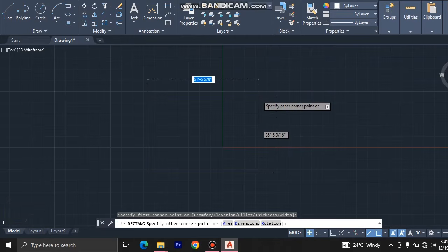As you can see, that is it. So put in the dimensions in inches. I've told you, you will convert 420 millimeters into inches, and so you will long press shift. If you long press shift, it will bring it up, then you will type 16.5. That is 420 millimeters, 16.5.